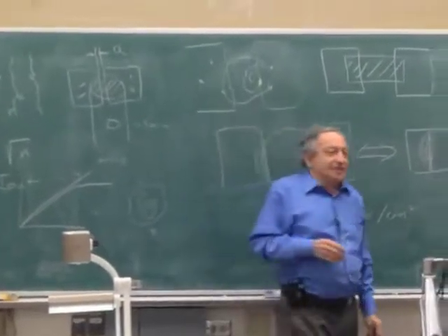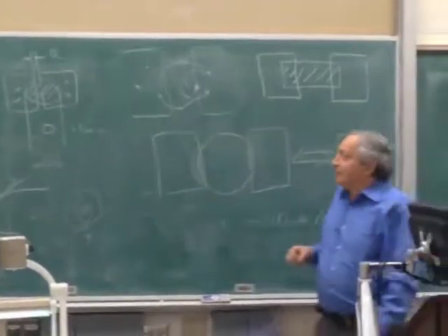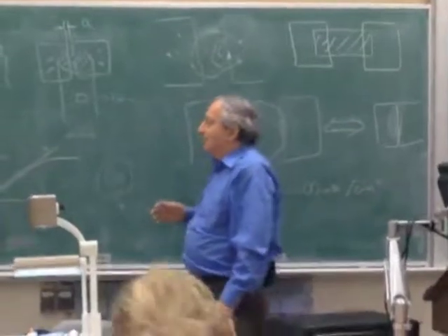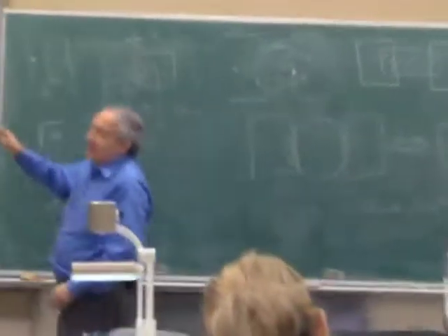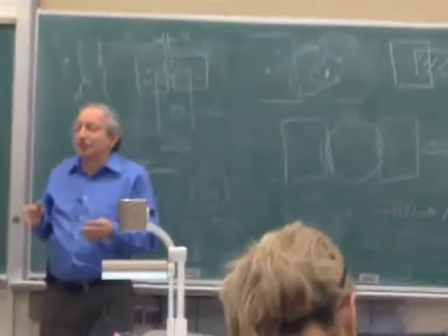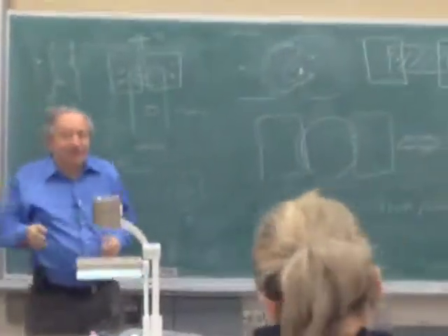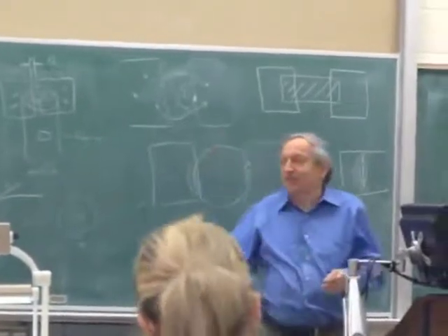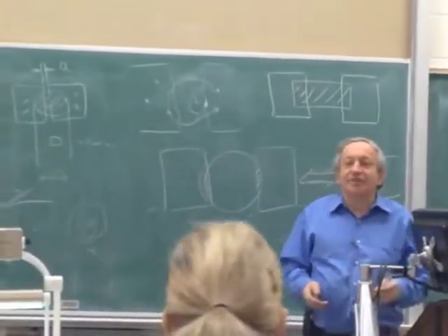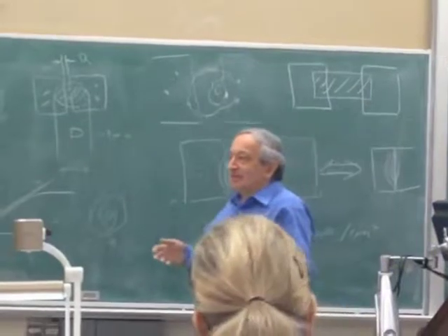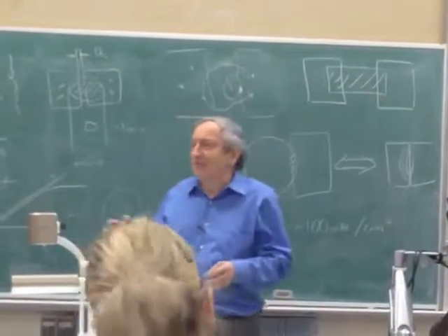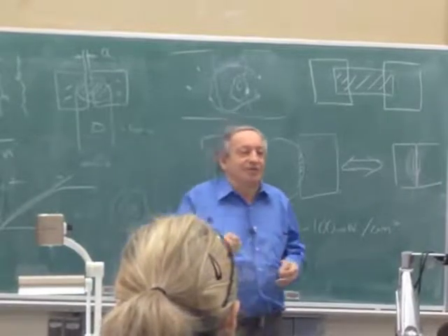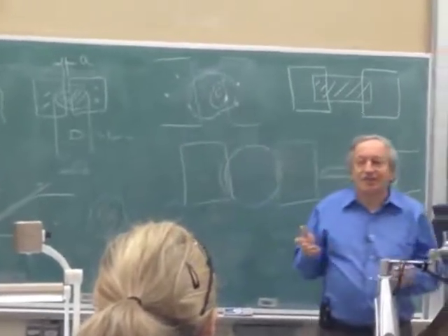Okay, now the last thing I want to tell you is another rule of thumb which is very, very important to design these detectors, because most people don't have an order of magnitude idea. If I take a laser pointer and shine it on a piece of silicon for the sensor, the laser pointer is in the range of milliwatts. All laser pointers are like 1 to 10 milliwatts. So if I shine a milliwatt of light on the detector, what current do I get?